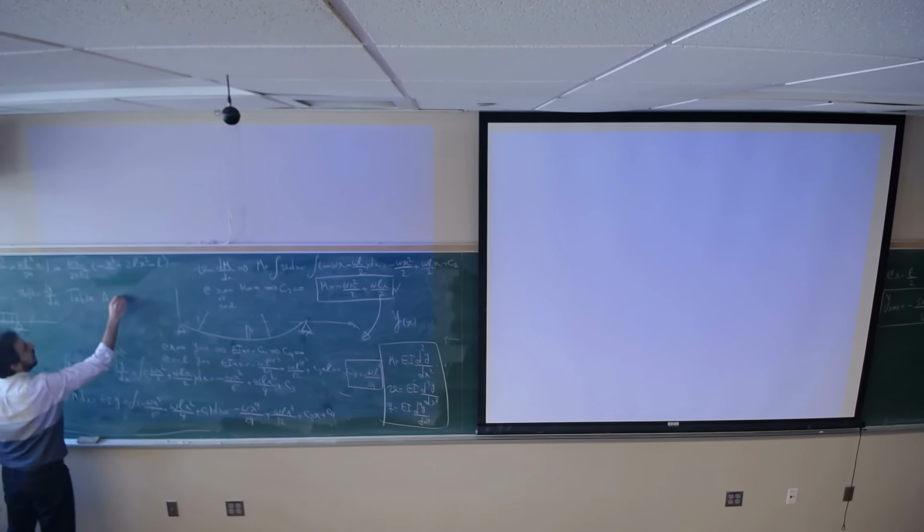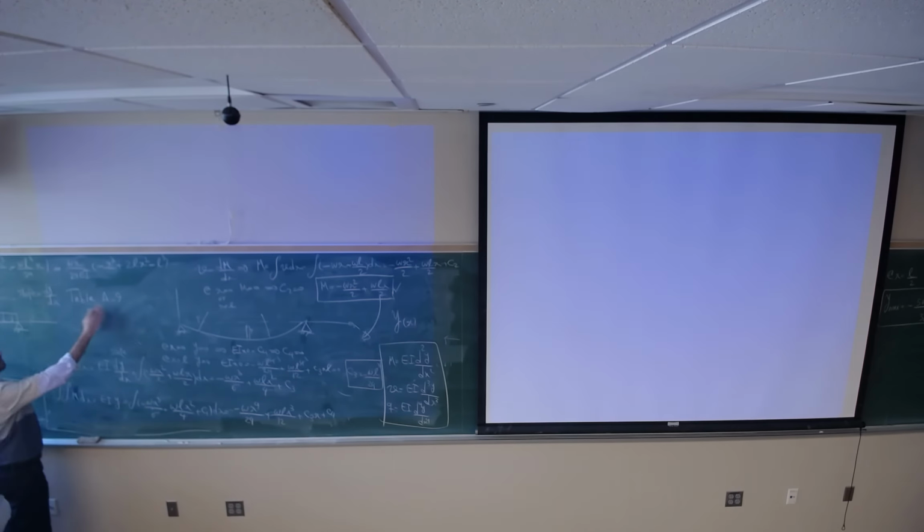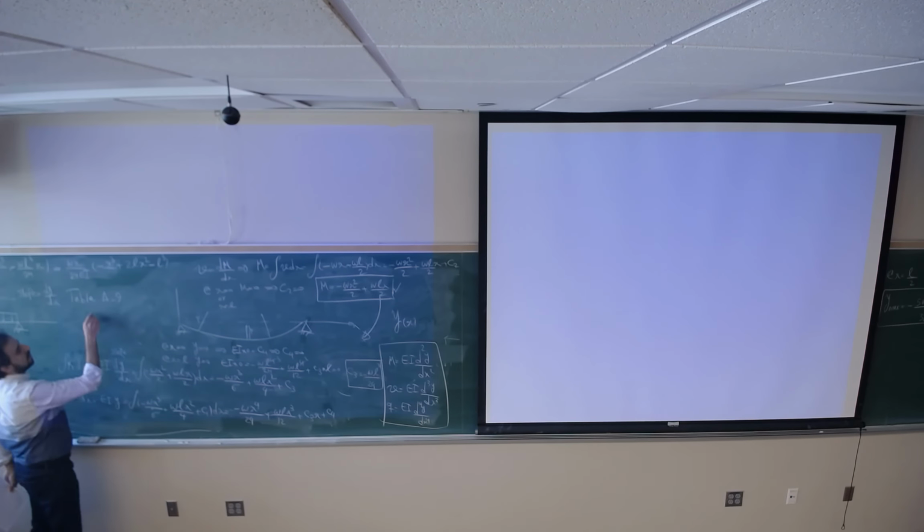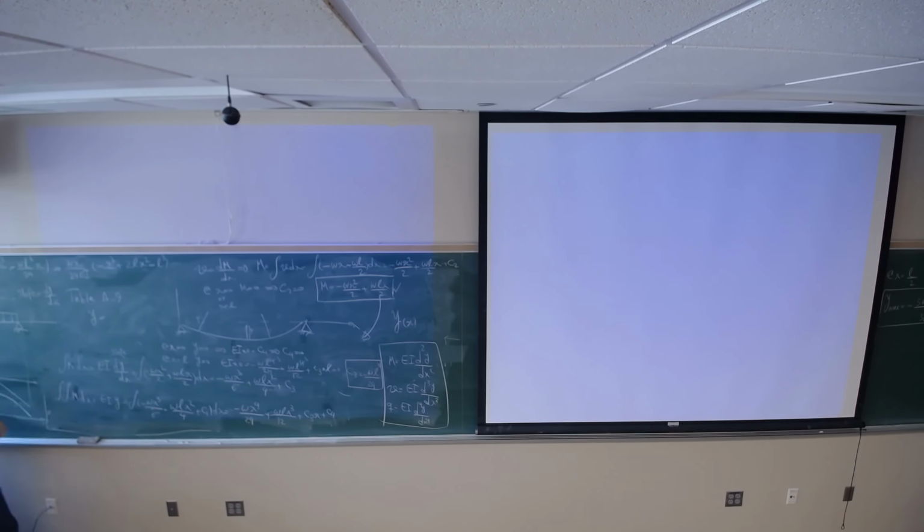Table A9 has provided some standard configurations. For example, you can find this beam with the loading of W as a distributed load with the length of L, and you can find Y by this function on Table A9.